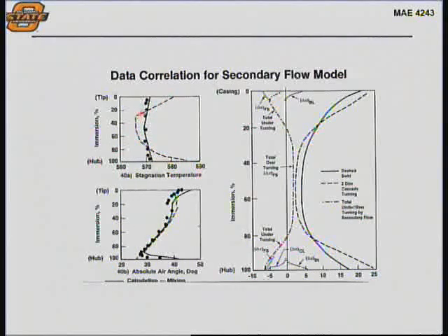So you get a fairly significant difference in stagnation temperature between near the tip and near the hub. If you incorporate the secondary flows, the fact that the flows will move from the high pressure to the low pressure side, and as it moves through the turbomachinery, it actually mixes the flow more.